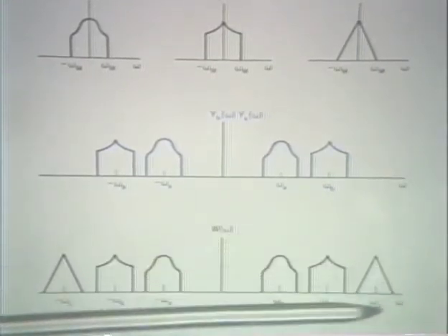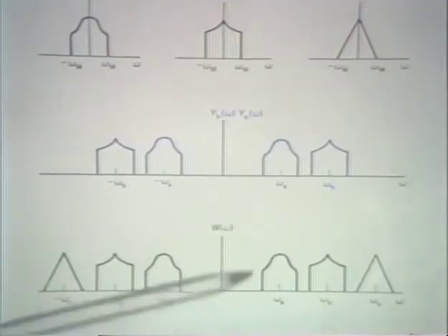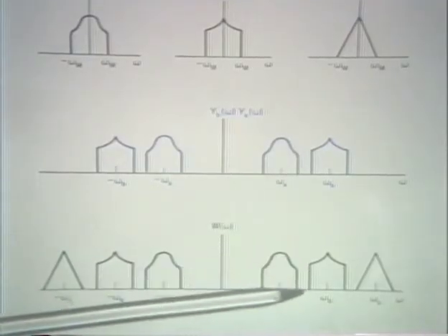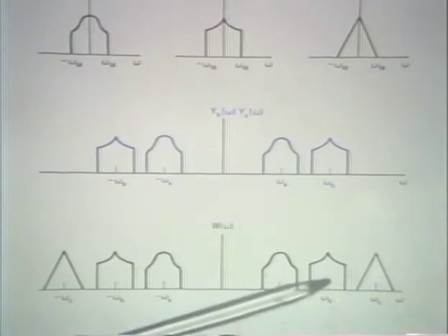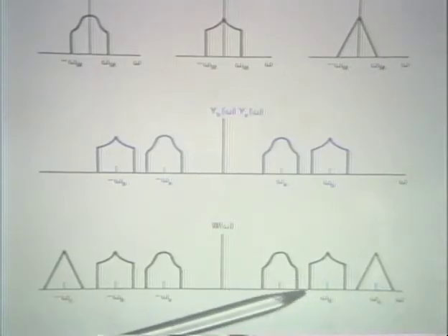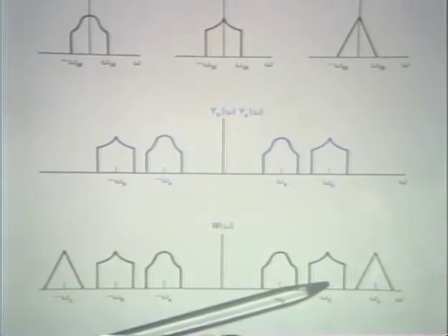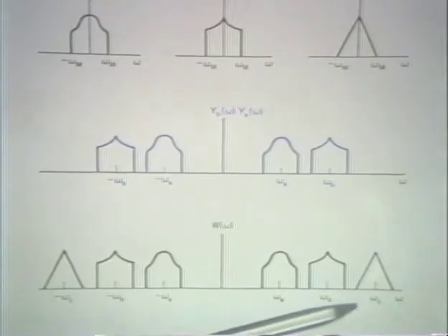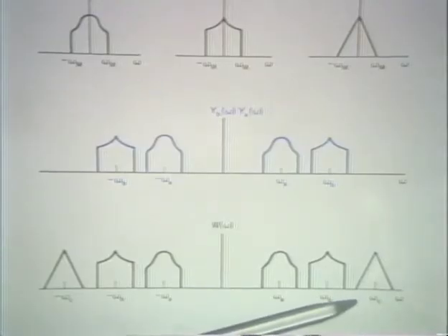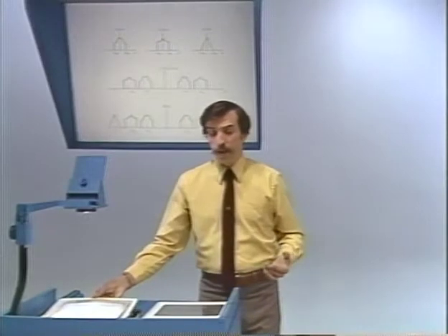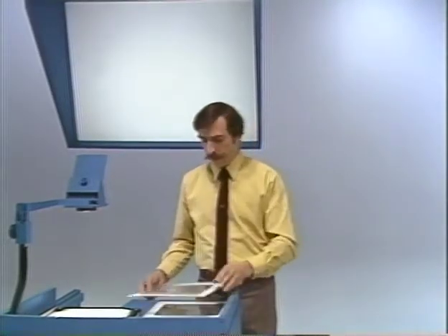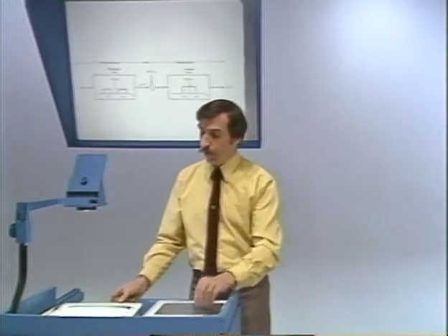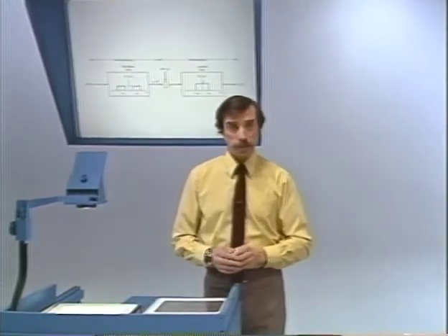And as you can see, essentially, by doing appropriate bandpass filtering, we can pull out whatever part of the spectrum we choose to, and then demodulate that in the appropriate way. And of course, we can do this not just with 3 signals, but perhaps with tens or hundreds of signals. So that's a process that is typically referred to as multiplexing. And as I've described it here, it's referred to as frequency division multiplexing.